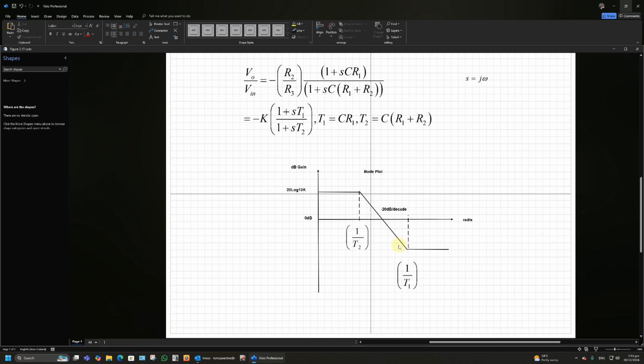And what it does is it increases the gain at low frequencies. It's like an approximate integrator, because an integrator is minus 20 dB per decade. So a pure integrator would just be integrating from DC up to daylight. It would just keep going all the way down, minus 20 dB per decade, and have infinite gain at DC. But this has got finite gain at DC, so it's not so good for steady state error and so on. It does improve the steady state error, but not as much as a pure integrator would. So you might think again, why not just use a pure integrator? And yes, we would if we could get away with it.